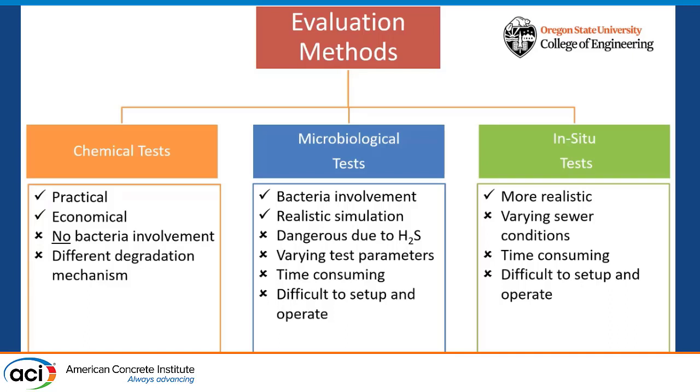This is a more realistic simulation, but the test parameters might vary a lot from lab to lab. And these tests are usually difficult to set up and operate, and they're time consuming. And we have in situ tests in the field. These are the more realistic tests, but they might vary depending on the sewer conditions, and these tests require a lot of effort and time.